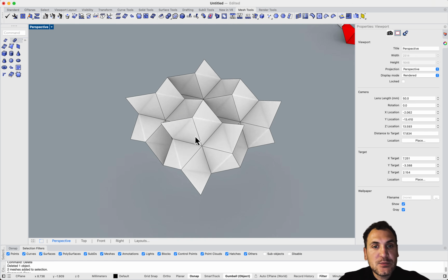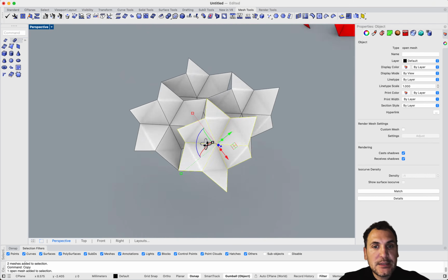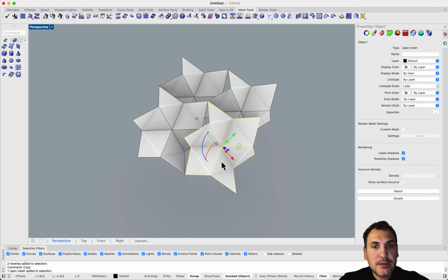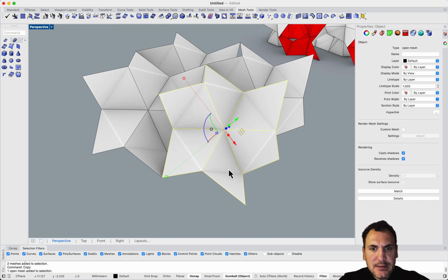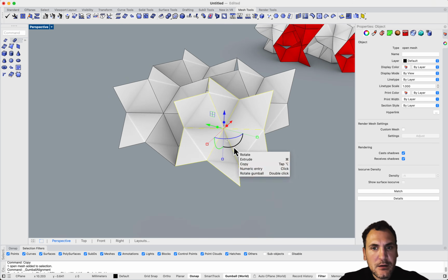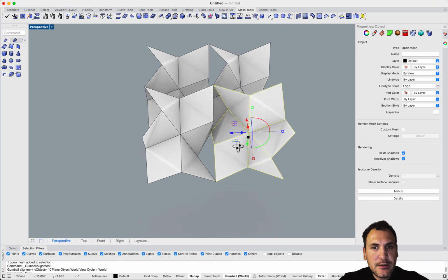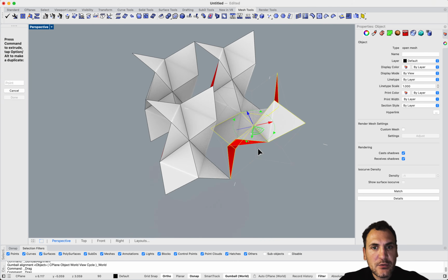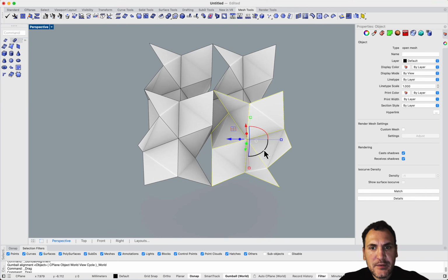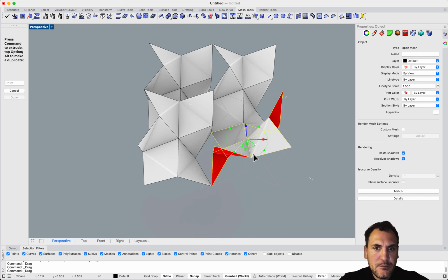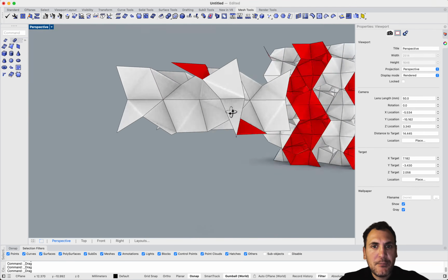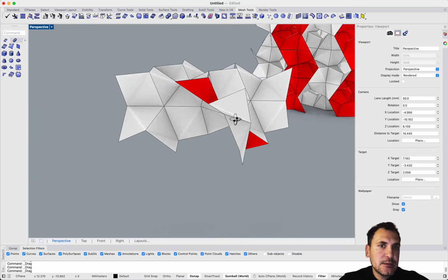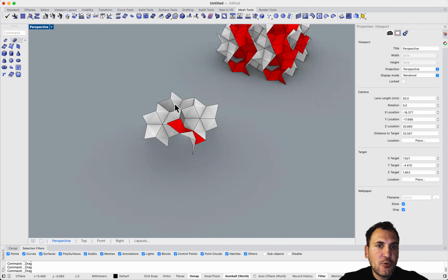For instance, this one, you can see that we need to rotate it somehow, but it's actually 2 rotations. So I need to first reset my gumball to the world, and the rotations are along this plane 90 degrees, and we should do a horizontal. Let me see this side. Actually, maybe it's this side. Yeah. So something like this that creates that type of void shape.